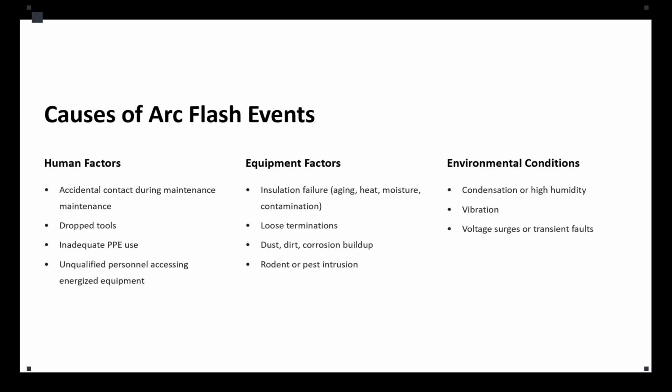Now, we could have voltage surges or transient faults. This is also considered an environmental condition for our equipment. Events like lightning strikes, capacitor switching, or motor starting can induce transient overvoltages that could exceed the dielectric withstand of the air that we talked about, initiating an arc even in well-maintained systems.